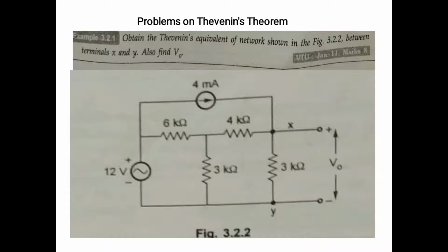In the last class I explained Thevenin's theorem and how to apply it. There are several steps. First, remove the branch impedance through which the current is to be calculated. Second, calculate the open circuit voltage across the terminals by using any network simplification technique. This voltage is the Thevenin equivalent voltage, VTH.